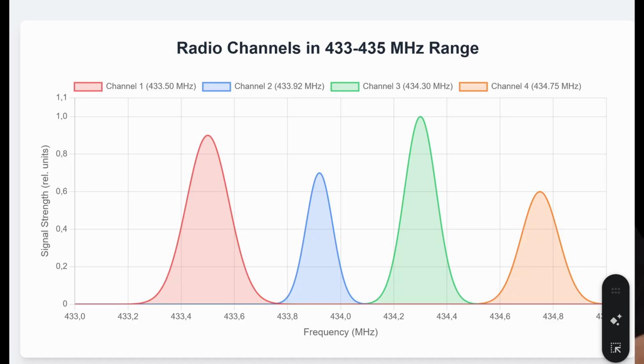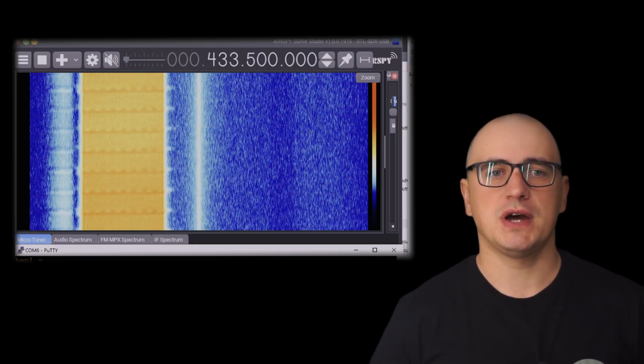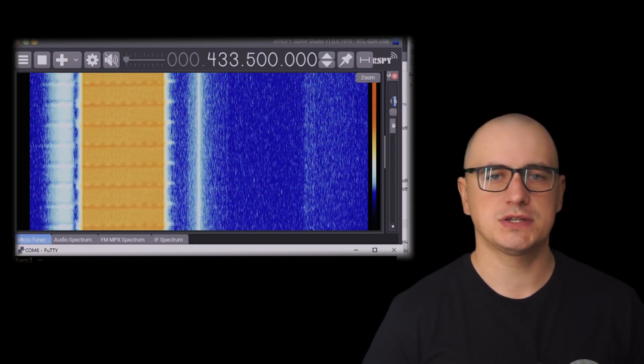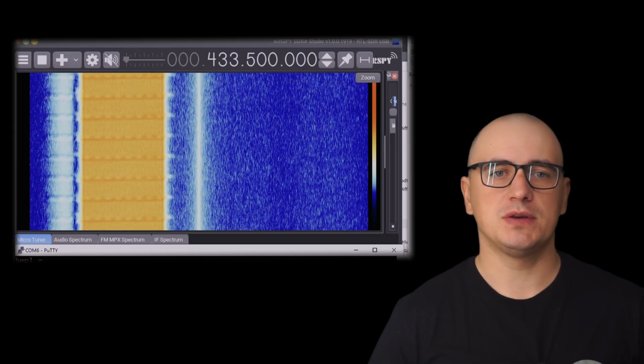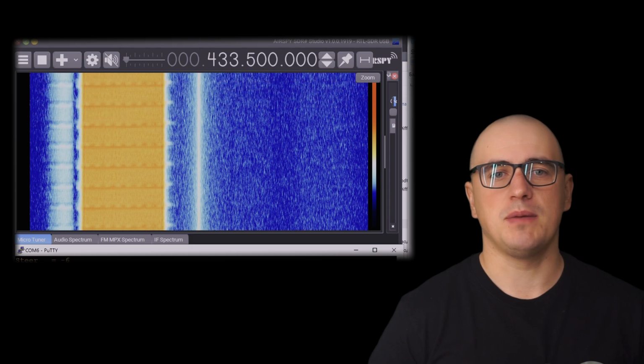Back in the early days of radio control equipment, the control signal was analog. Each command used its own frequency. This number of frequencies the equipment can transmit on is called the number of channels. Now everything has changed. We have started transmitting digital commands, so we can transmit multiple commands on a single channel, but the name remains the same.